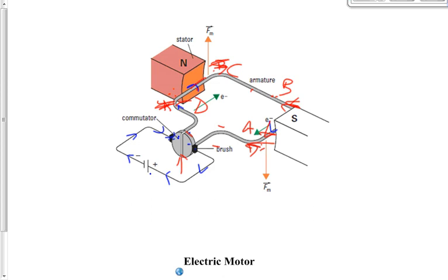So the left side of the wire, every quarter revolution, is just moving because it's got momentum. But at other times, the left side of the wire is always being pushed up. The right side of the wire is always being pushed down. So the motor ends up spinning like this because the left side is always pushed up. The right side is always pushed down. Does that make sense?